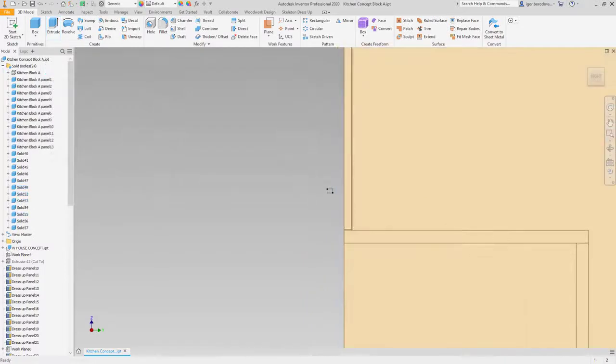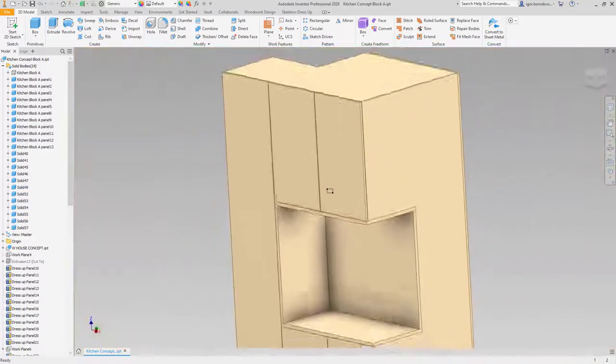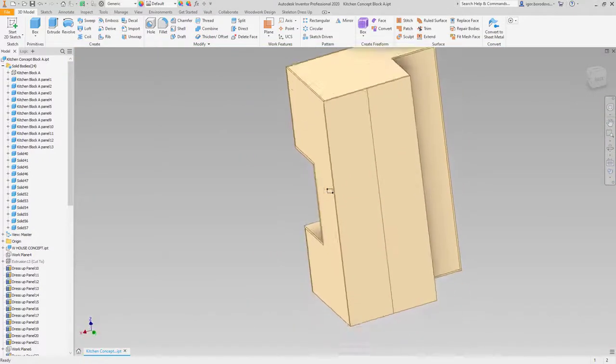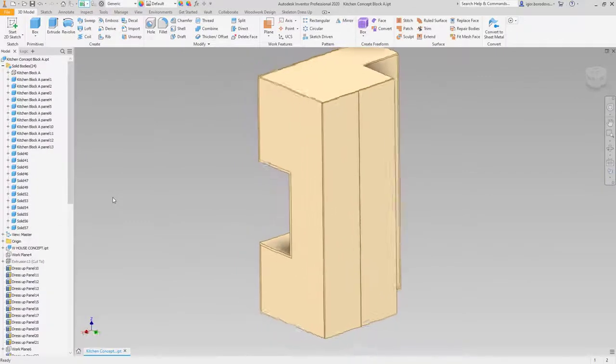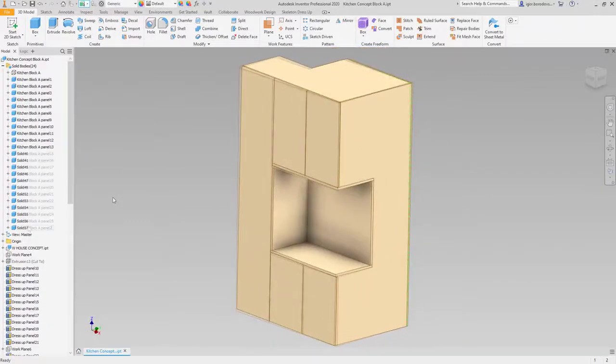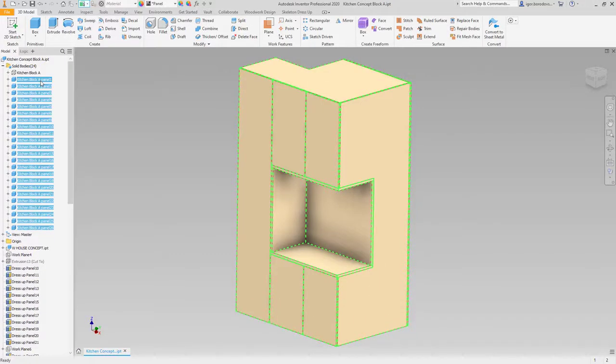As you can see now, the door leaves are in the correct shape and the correct thickness, so the same can be done on the opposite side. Since we have finished the skeleton design stage, solids can be converted to new parts and then combined into a new assembly.